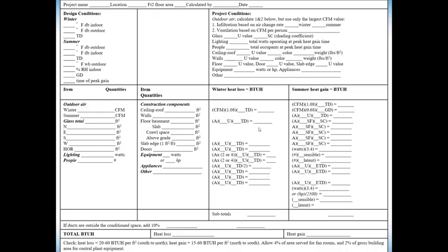And during the summertime, it's 75 for the authorities' recommendation and 70 for people's preferences. That's how I remember, if I'm not mistaken. It's in the previous class, and we are definitely going to check those slides. And for the design conditions, it's going to be the indoor dry bulb temperature, and outdoor is whatever the outdoor is.